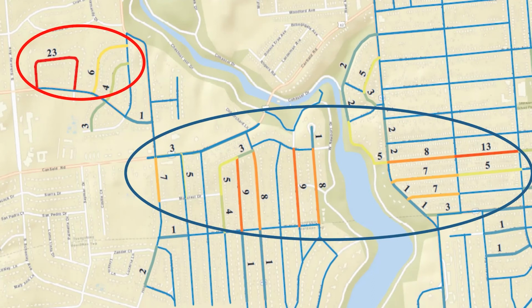I've seen situations where the pipe that got installed on a Friday is the problematic stuff because people weren't paying attention. So, what this allows you to do is visualize patterns. So we can see here that most of the pipe in this area that was generally thought of as very bad is actually in great shape. Some have had maybe only one break in the last 15 or 20 years. And if you want to make a quick impact, you could do some very specific focused pipe replacement and knock your break rates and your water loss and everything else associated with that down fairly considerably.